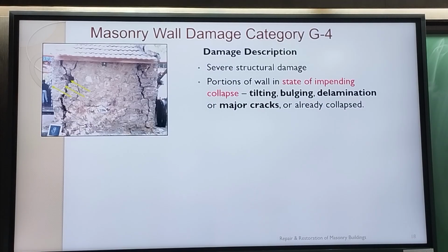And it doesn't happen only in stone walls, it also happens in brick walls. Brick walls which are like 13 inches and 18 inches thick. Because the old masonry buildings were multi-story, we had walls which were thicker than 9 inches. So if these walls are not made properly, the bonding is not done properly, then that delamination can take place.